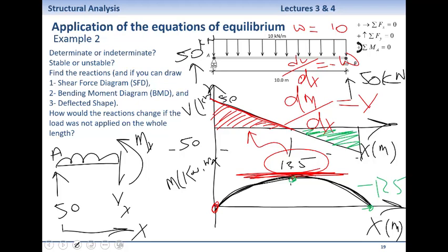So, just before I wrap up, method of sections, which is a very solid way of calculating reactions, shear forces, bending moments, is still applicable. We want to be a master of method of sections, calculating shear force and bending moment diagrams using equilibrium, yes?